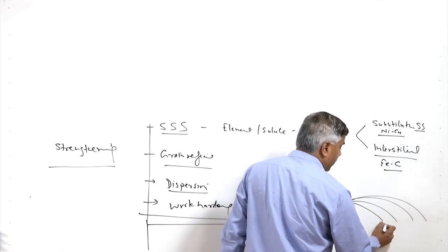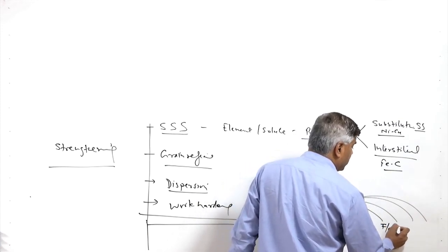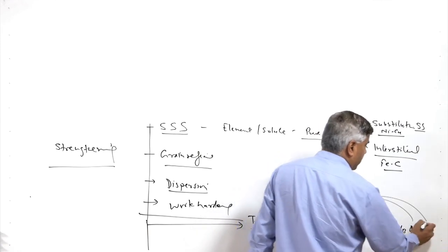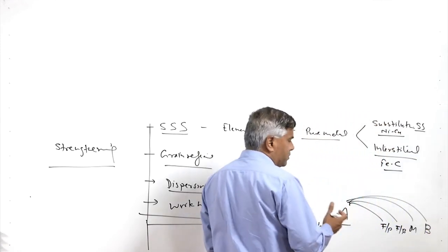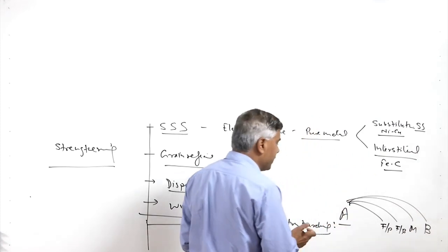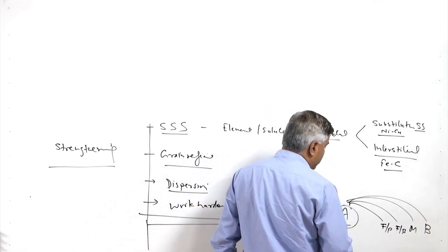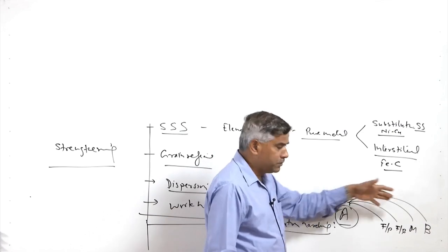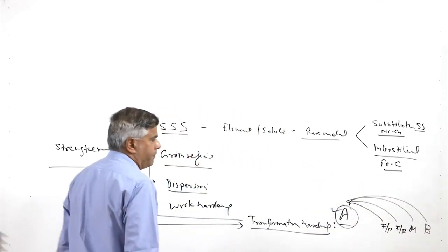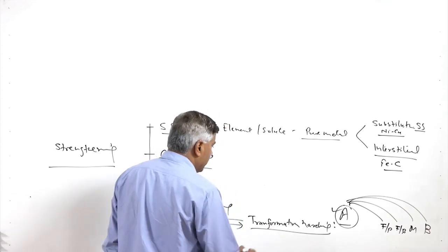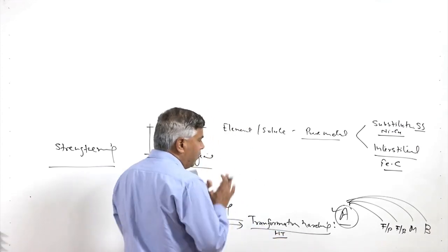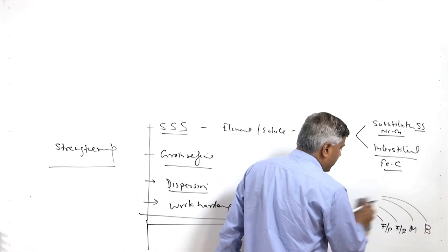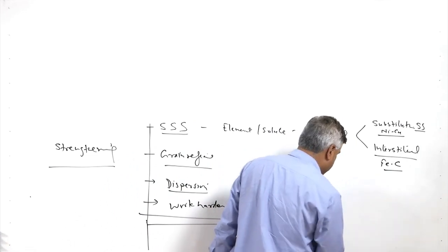It may lead to ferrite, pearlite, or ferrite, bainite, or martensite, or bainite only. So, a variety of constituent phases in different proportions are possible by controlling the cooling rates during the heat treatment. So, one phase is transformed into different phases in order to realize a different set of properties. This is one of the approaches of heat treatment, where one phase is transformed into different phases in order to regulate the properties as per the requirement, and accordingly different types of heat treatments have been developed.